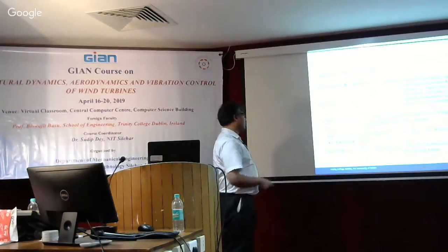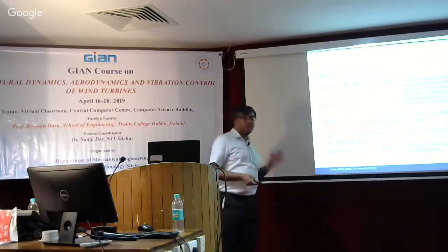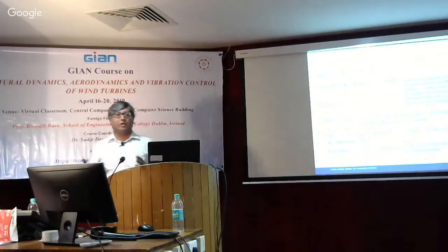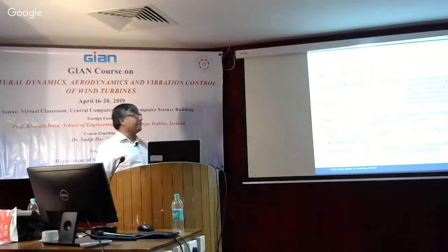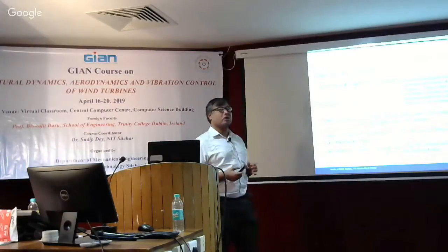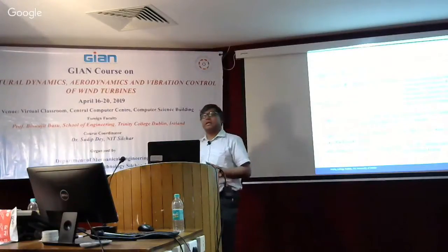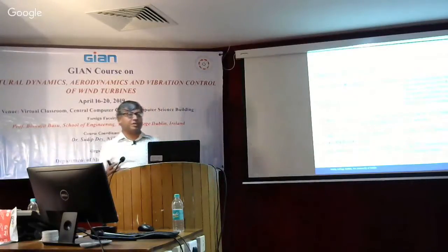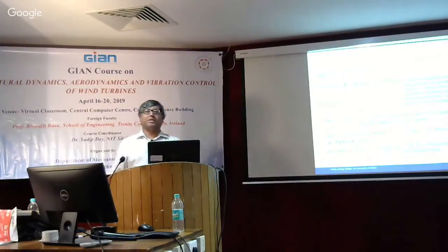But you can see that we have taken the non-rotating frame and then converted that into the rotating frame. That's really what we have done here, and it shows you why this sort of modeling that we have done with the Coleman transformation is very useful, because then you can directly use it and solve the optimal problem. A note of caution, this solution of optimal control law is again not trivial. As I said, like in the case of model predictive control, or there is also a robust controller, there is a technique called linear matrix inequality, which you can solve.